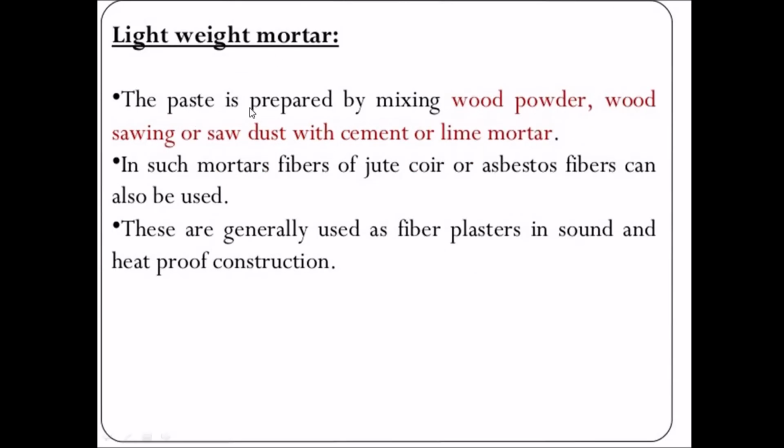Lightweight mortar: the paste is prepared by mixing wood powder, wood sawing or sawdust with cement or lime mortar. In such mortars, fibers of jute, coir or asbestos fiber can also be used. These are generally used as fiber plasters in sound and heat-proof construction.